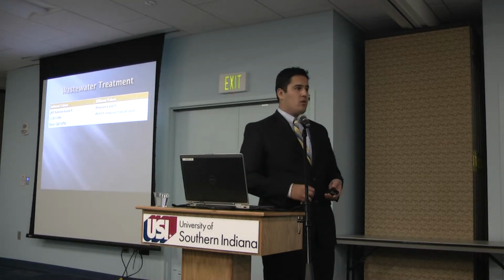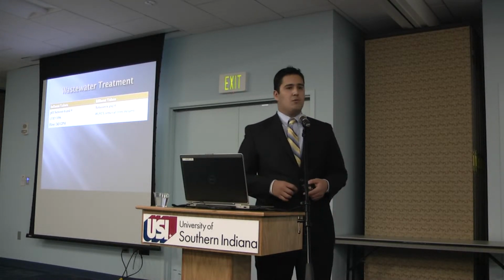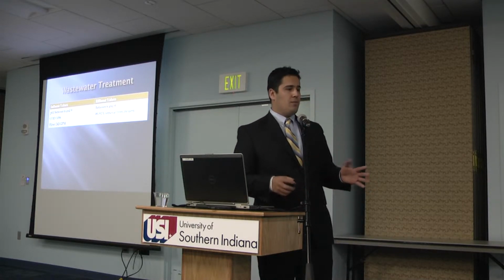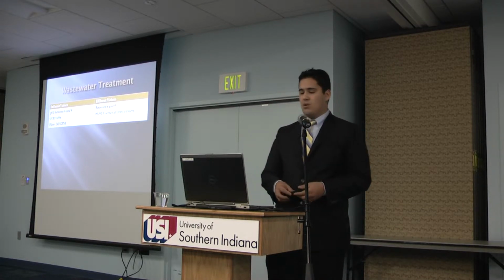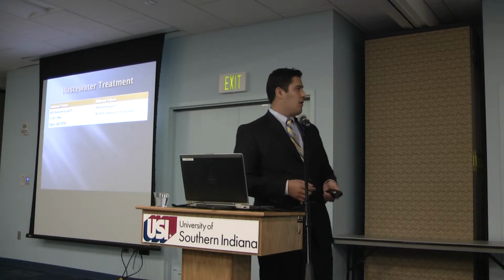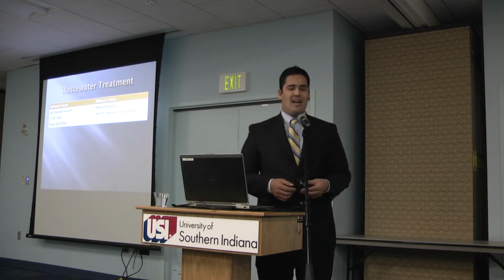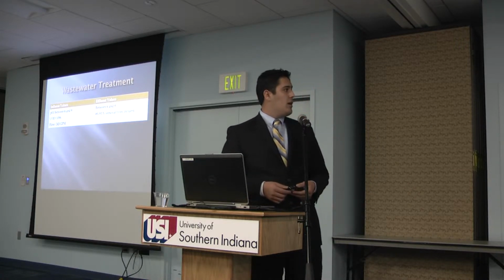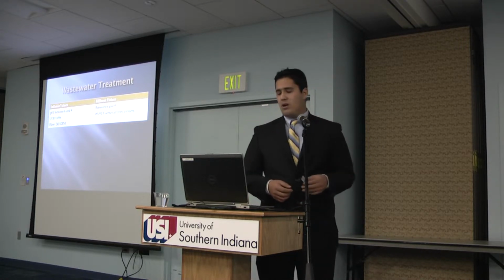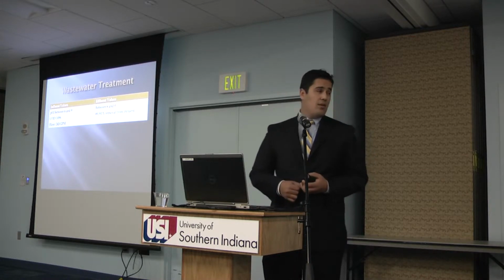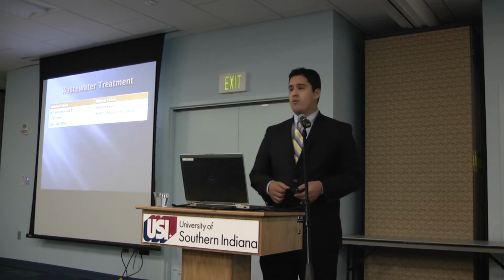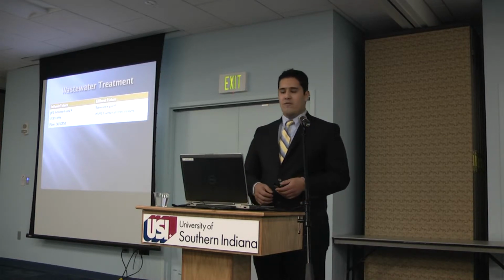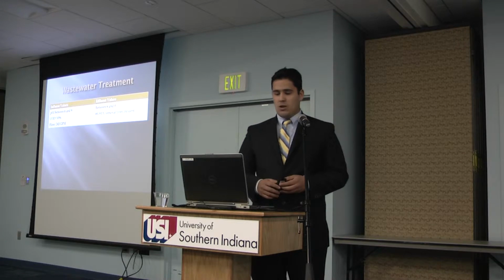The wastewater coming to Abengoa has a pH between 6 and 9, and the water leaving will have the same pH. The COD, the chemical oxygen demand, is about 1,096 in the influent water. And as it comes out, it goes down to 99. That means it's a 91% removal from the influent water. The regular flow is around 245 gallons per minute coming into that tank.